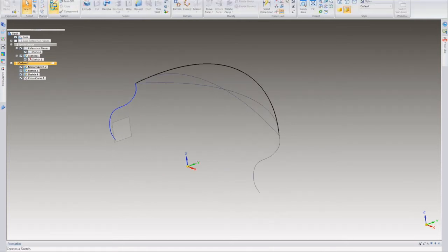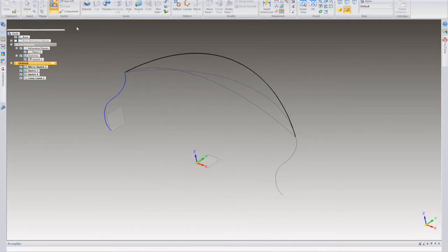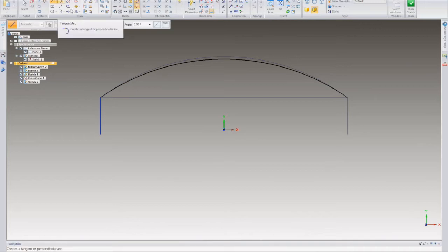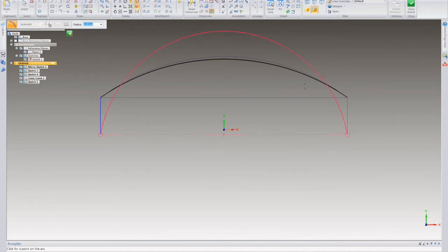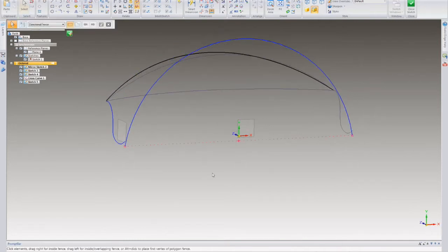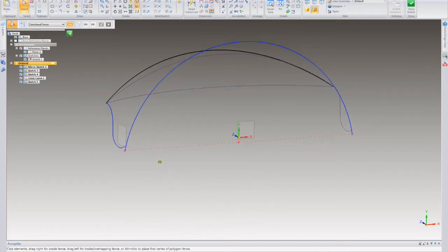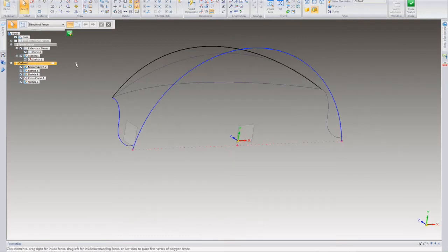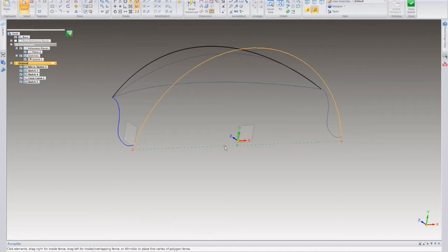I'm going to go ahead and quickly do a bottom sketch just to control this. So again, I connect that bottom one at a point that was normal to my reference plane. So I'll just use that point in space. And I'll just quickly create that guy. I'm going to go ahead and leave that disconnected just to show you. That's what happens when you don't actually connect in space sometimes.